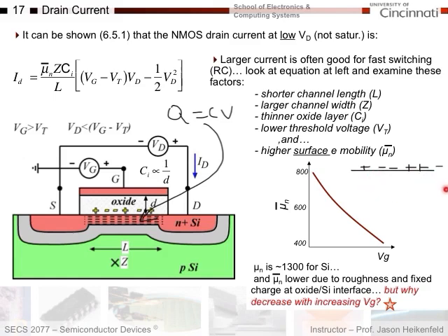That's a pretty zigzaggy path, isn't it? The more zigzag it is for the electron, the easier it is for it to run into silicon atoms or other electrons. And so if you have more collisions because you're making it go more zigzaggy because of the electric field influence of these charges, then that decreases your mobility. And so I have a surface mobility, which I calculate, not a traditional mobility because of these interface charges here.